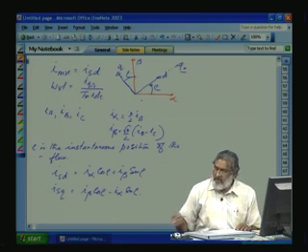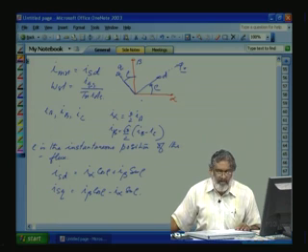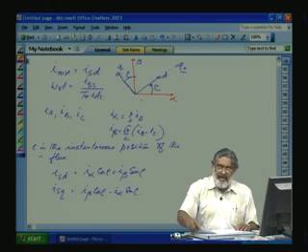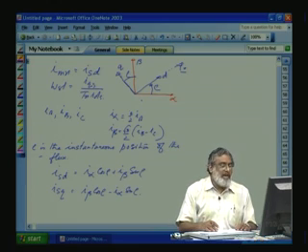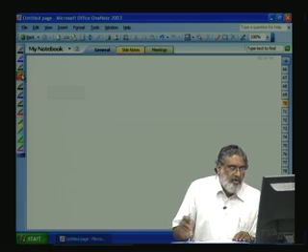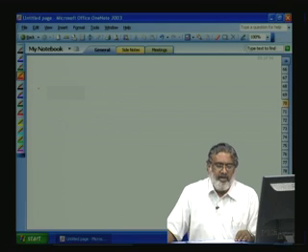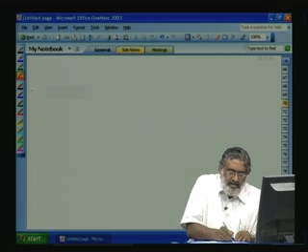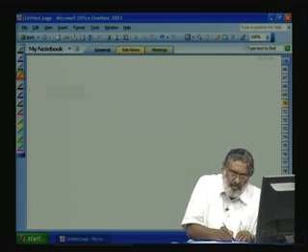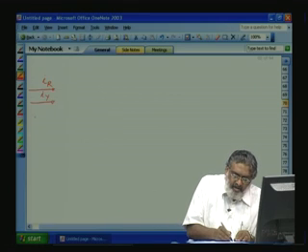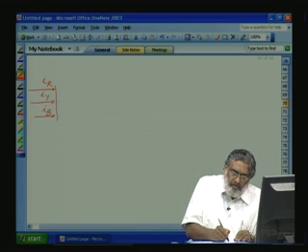Now from this, how do we find out the equivalent circuit? Let us try to draw the induction motor model under field oriented control. We will draw the induction machine model when the correct field orientation is achieved. So we are sending the three-phase currents to the motor, that is IR, then IY, and then IB.